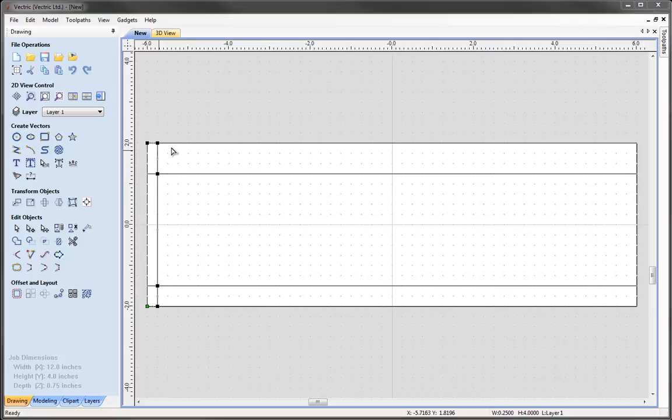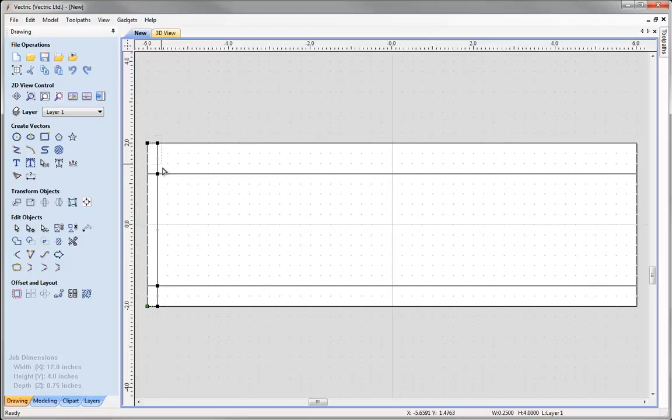Okay, to select multiple nodes, using the mouse, I'm just going to draw a rectangle, using the left key on the mouse. That's going to select all of those nodes where I've put my selection in. And all I'm going to do is select one of those and just drag them over to move that over. So now we've moved that over by 1/4 of an inch, and we know the distance between this node here and this node here is now 1/2 an inch.